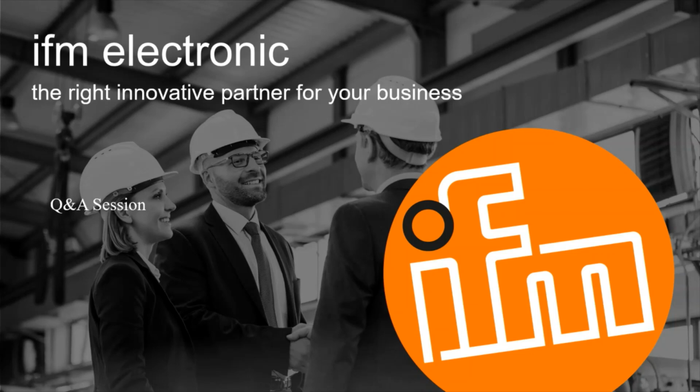Then, can the LDH humidity sensor be used to detect moisture content in air? Normally the LDH100 is marketed a lot for oil applications. However, it can be used in air applications as well. You have to make sure that the pressure in your system is within the range of the sensor so it can handle it. Another important thing is that at the factory, this sensor is calibrated using air. So it most definitely can be used for air applications.